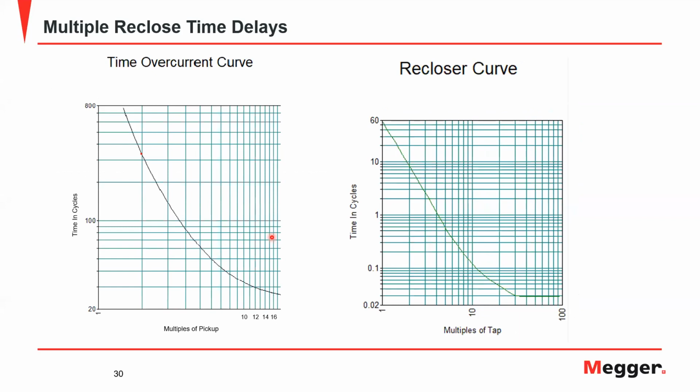But we're also talking about reclose coordination. Reclosers have similar curves, but they're shaped differently. And this is just a random curve that I selected. Didn't have any rhyme or reason to it. Reclose curves come in many different characteristics. Some curves come out here and do odd shapes like this. A good number of them will come in here, drop steeply, and then flatten back out this way. But you have to be able to overlay these onto a common graph, do a study, and be sure that this curve is functioning behind this curve. And I'll explain that in a moment.